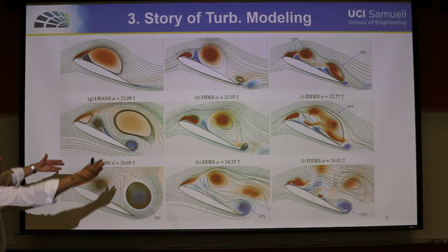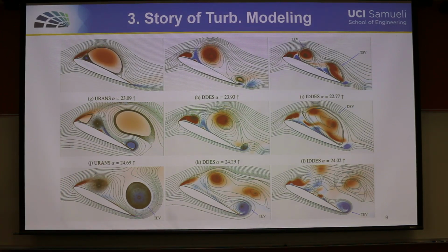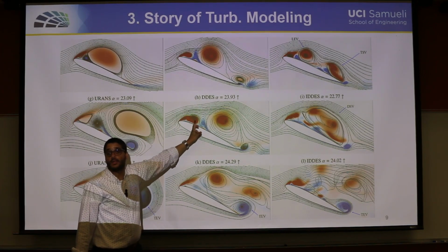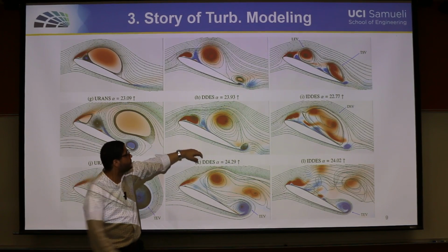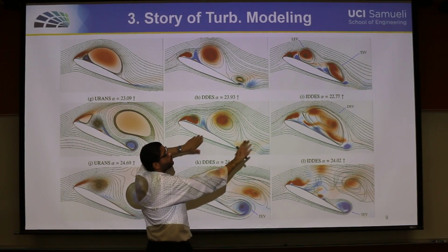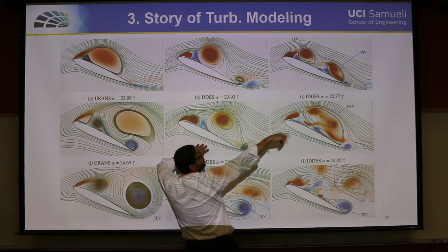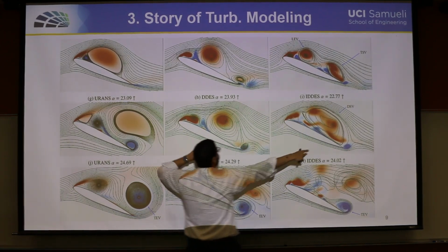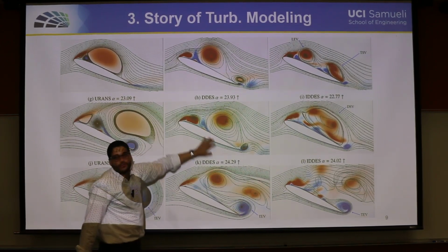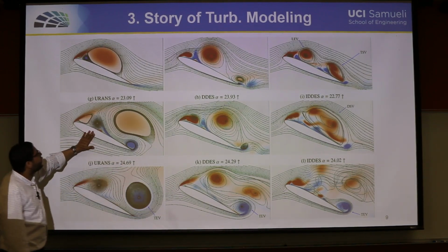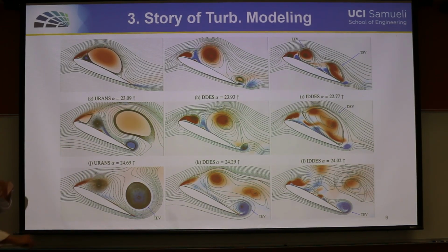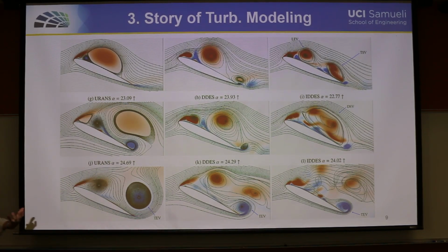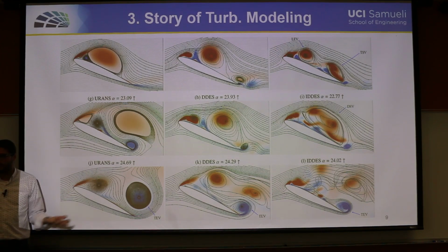Again, this is a difference between the three of them. This is the unsteady RANS, and this is the DDES. There is no wall modeling here. This is the delayed detached eddy simulation, and as you can see, there is a difference between it and the improved one. The wall-modeled LES gives you better resolved turbulent scales over the turbulent boundary layer. Here, the solver is kind of trying to capture all these scales. Here, good luck with those scales. So I'm not trying to put the RANS modeling in a bad light, but you get what you paid for. That's it. Okay.